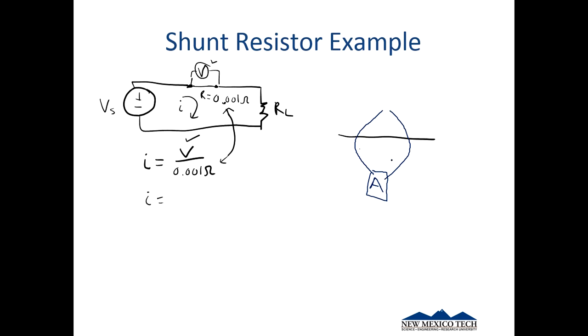In fact, it's really good for things like, is there current flowing through here? But for a piece of permanent instrumentation, it doesn't work out really well. It's really good for checking to see if there's current flowing, but not so great if you need to be monitoring current for hours and days and weeks and months. It's better to just use a shunt resistor.